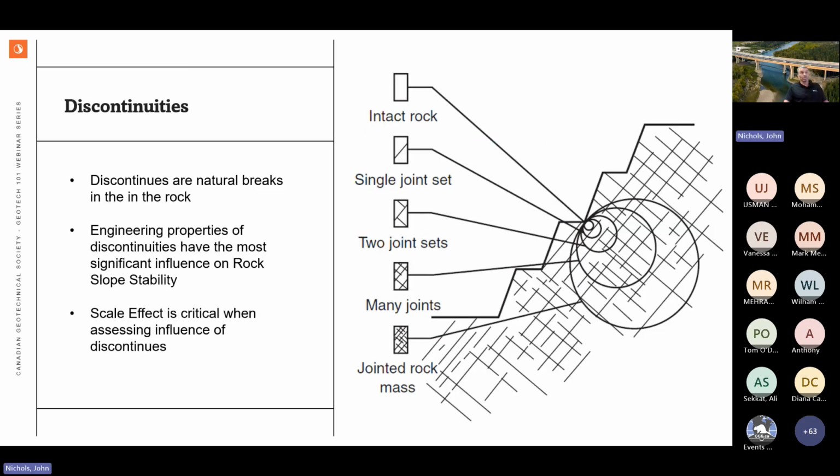Okay. Like I said, these discontinuities are natural breaks in the rock. Typically rock masses contain networks of these, and they develop through geological history. These discontinuities control rock mass behavior at a large scale, including strength, deformation, permeability. If we look at it in a holistic view, discontinuities are very important in the mining world. They're often associated with complex structure where mineralized zones occur. So for engineers working in that field, understanding the mechanical properties and the engineering strength of those discontinuities is key.